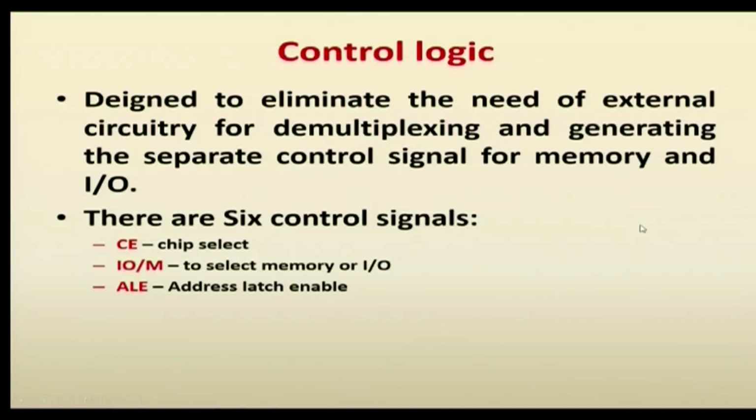So, automatically the speed is increased without using additional circuits, because it also avoids the propagation delay. When we are interfacing with peripheral devices, first we have to connect the address lines where we want to write, because we have a number of ports. Which port you want to select, you give the address, then the data you want to send to the display device is also made available on the data bus.